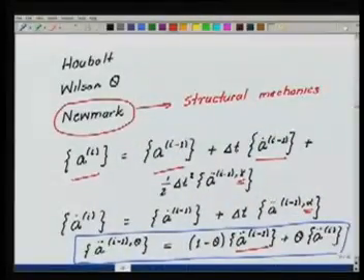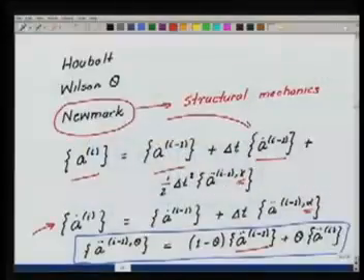Here we assume that the solution is completely known at step t I minus 1. Similarly, the velocity at step I will be given in terms of the velocity at step I minus 1 plus the part due to the accelerations. So this is how we are going to update the velocity. Here, the way we have done things explicitly, we do not need to use the velocity in the formulation, but the velocity has to be updated so that it can be used here.